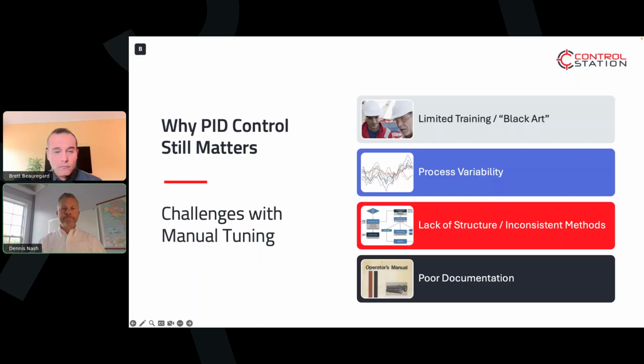Next slide. So that being said, one of the benefits of PID is that it's easy to fiddle around and get something that at least is safe, right? The first thing that the regulatory control system is there for is to make sure that things don't run away. If everything's in manual, you're going to be running far from that plant. And so just having the PID in place is of benefit for safety.